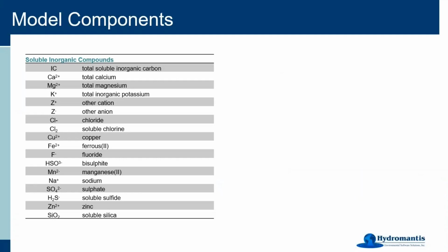First and foremost, what we wanted to do while developing this platform was to work with some principal components that are there in the water. So rather than looking at composite parameters of alkalinity, for example, hardness, and so on, we wanted to look at fundamental components that we can then make a mass balance on.